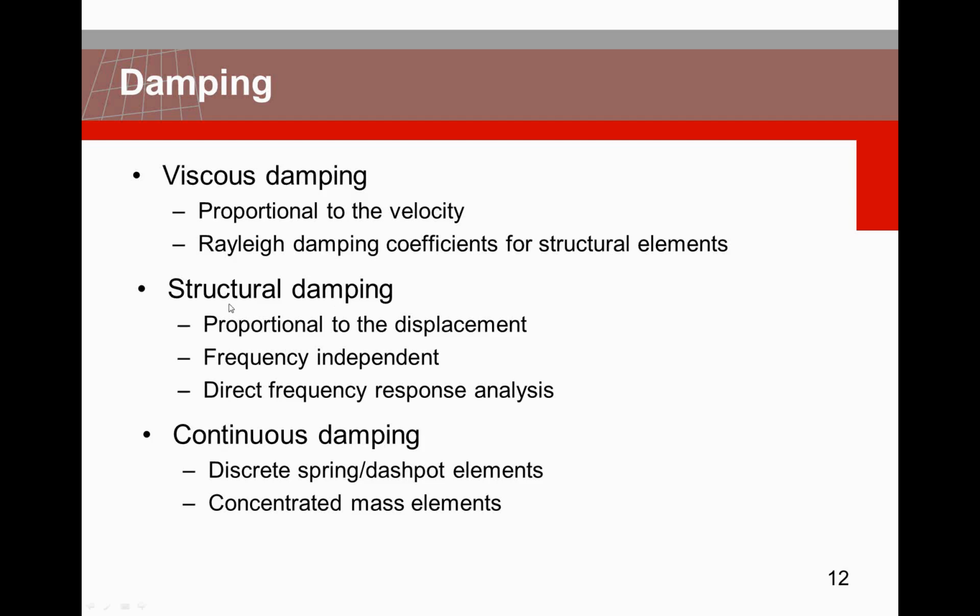Next to that, we have structural damping, which is proportional to the displacement. It's not dependent on any frequency, and this type of damping can only be applied in a direct frequency response analysis.